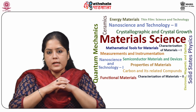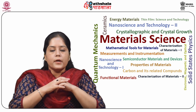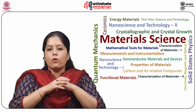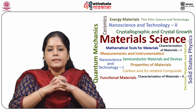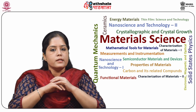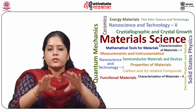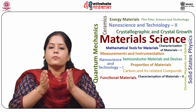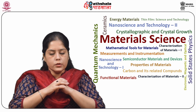Now CCDs have been classified as first, surface channel CCD, that is SCCD; second, buried channel CCD, BCCD; third, peristaltic CCD or PCCD; fourth, profiled peristaltic CCD or PPCCD. Now, before studying the operation of CCD, it is important to study the transient characteristics of MOS capacitor operating in deep depletion region. So the representation of information in a CCD is different from that of the transistors, where instead of charges, currents and voltages are used.